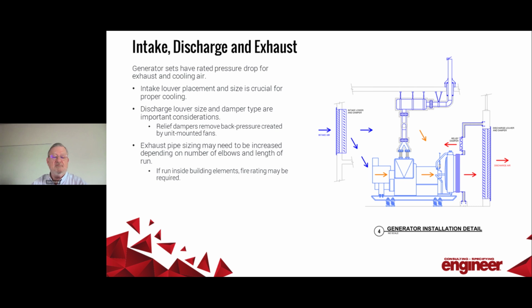So let's go into a little more detail on why we care about the size of our louvers. We know that there's pressure drop across a louver and damper, and that pressure drop is based on the amount of air we need to move. So when we make generators larger, for example, we need to increase the physical size of the intake louvers and discharge louvers. Those previous images were actually from a project in which we were doing just that.